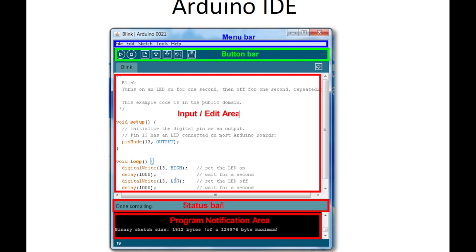Okay, and then there's a delay of 1000 milliseconds. 1000 milliseconds means 1 second. Then it's writing again to the same pin, making it low, meaning 0, and again a delay. So these 4 lines will keep on running forever, as long as you want.